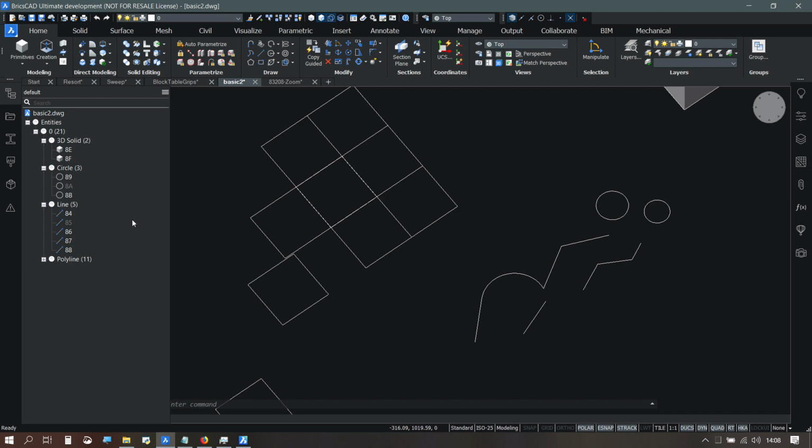So here we show a different color for the hidden and for the visible stuff. The visible stuff is bright white, the hidden stuff is faded. So if I only want to make this one visible again, I right click and say show. So I get my one entity back and not all the others that I've been hiding and that I want to keep being hidden.